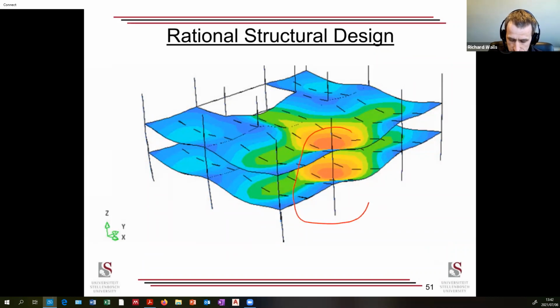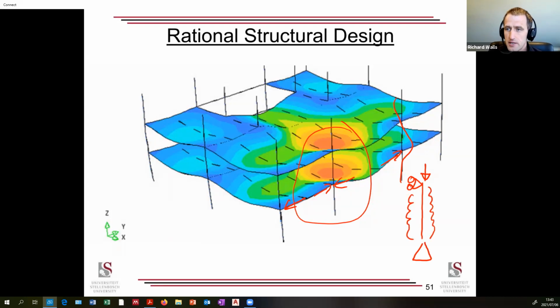You'd have a fire in a distinct area. It would heat up the slab, beams, columns, there'd be deflections, etc. There'd be induced forces. As things expand, they induce very high forces, and it's normally those induced forces which cause failure. So as this slab pushes out, it causes major bending on a column, causes the connection or the column to fail. Whereas in standard fire testing, we assume that it's a simply supported column with a fire from all sides. So it's a very different scenario.